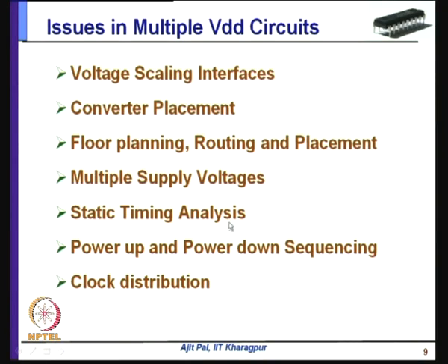So, when the entire circuit is operating at a single voltage, the static timing analysis, that means the delay of the circuit, can be very easily modeled and computed. However, whenever we are using multiple voltage levels and that too is changing with time, then static timing analysis becomes very difficult. This static timing analysis is very important for reliable operation of the circuit, because what will be the delay for different supply voltage, that has to be identified.